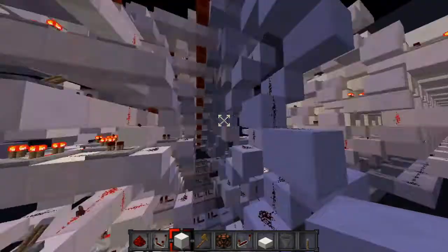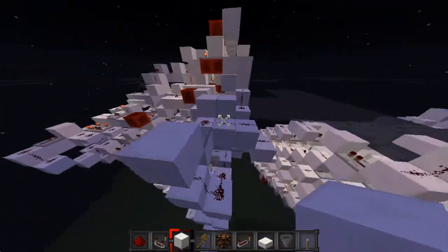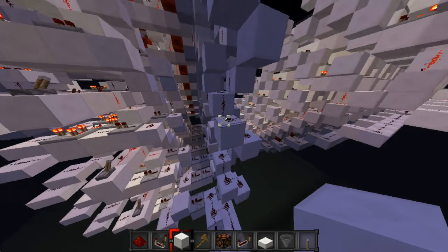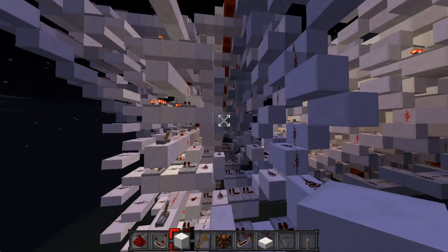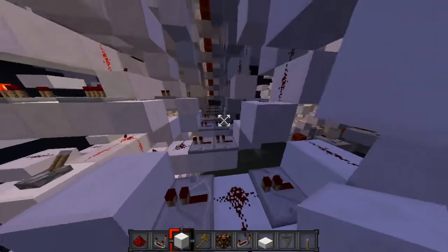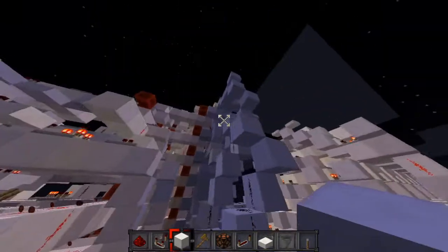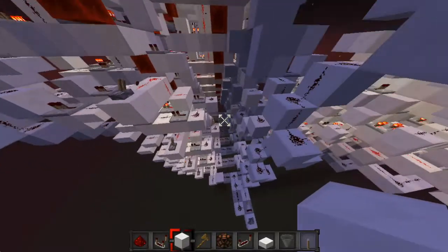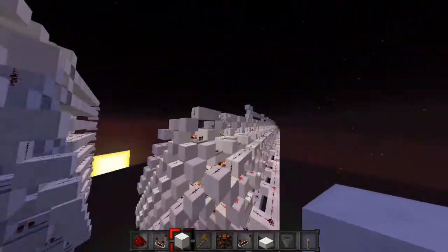You might remember that we don't directly output this output of the ALU back into there. We have to add some delay in there in order to make it so that the entire length of the loop is 16 ticks, so that there's 8 different, I guess we're going to be formally referring to them a lot as cores, even though maybe that's not the best technical definition. But in order to have 8 different cores on this circuit, we need the total delay on this to be 16 ticks, and we add that delay in here. So let's talk about the memory for a second.